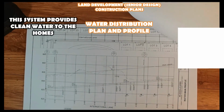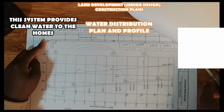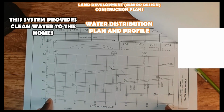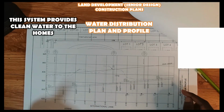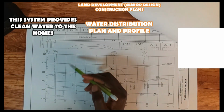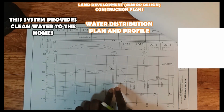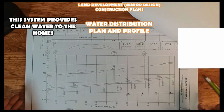Okay, so this is where things started to get very technical. It's one thing to just lay out where the utilities are going to go, but it's another thing to make sure that the system works. To make sure that it works, we don't only need the plan view, we also need to know what is going on in the ground, and that is where we have the profile view. This is the water main profile. This is how the water is going to be distributed along these homes. As you can see, lot 24 will connect right here, then 23, 22, 21, 20, and this is 19, and it keeps going all the way up.